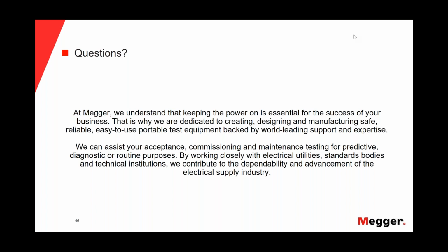If you have solid-dielectric, they have typically lower acceptable levels than fluid-filled terminations or splices. But like I say, the 1000 in the field is a number that when you measure it, you need to do something about it. It's a warning flag, where the 5 pC is what it should be when it leaves the factory.